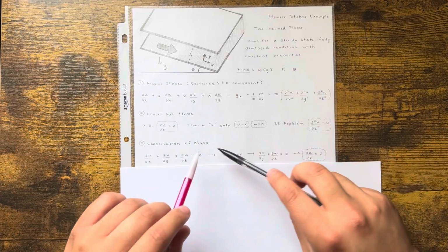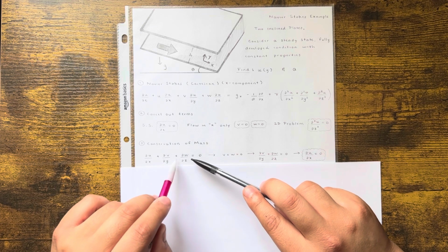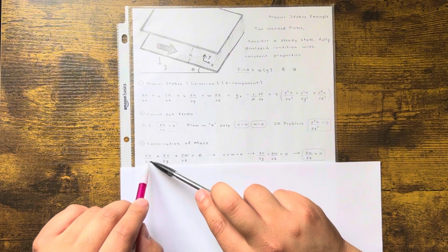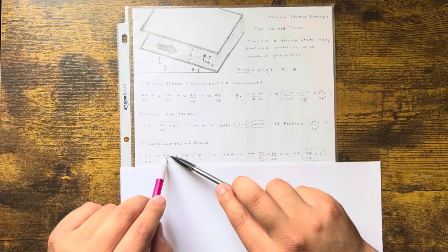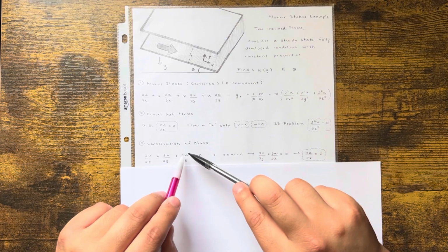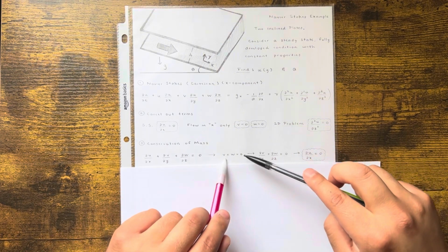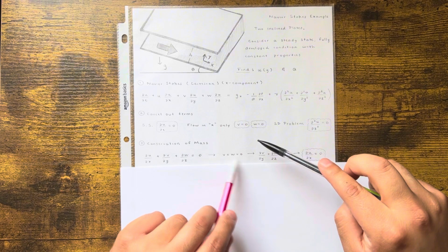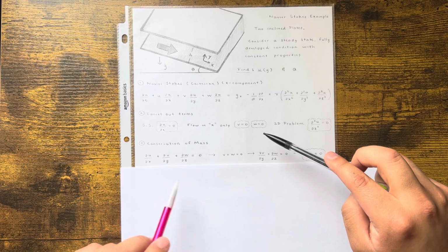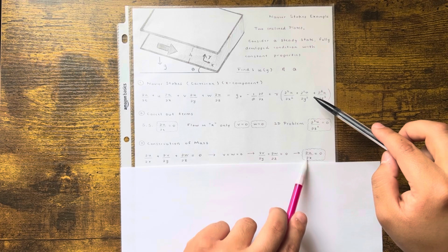Conservation of mass for an incompressible fluid tells me that partial u over partial x plus partial v over partial y plus partial w over partial z is equal to 0. The change in velocity in the x direction with respect to x, plus the change in velocity in the y direction with respect to y, plus the change in velocity in the z direction with respect to z is 0. Well, we already determined that there is no flow in the y or the z. So take the partial of this with respect to anything, you're just going to get 0. So 0 and 0. That means this is equal to 0. And that's what I kind of wrote here.